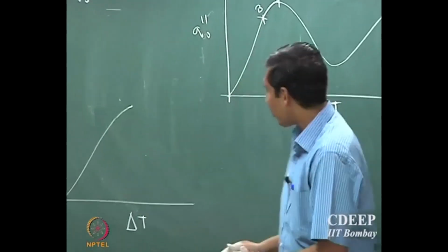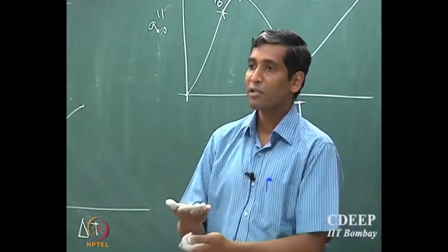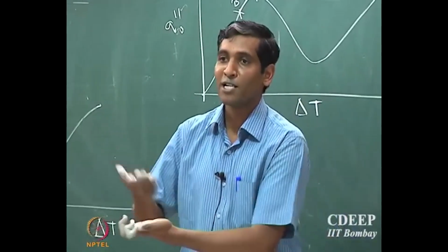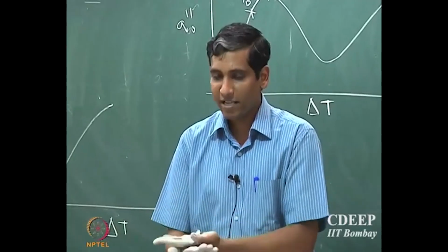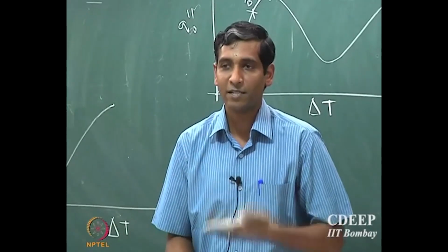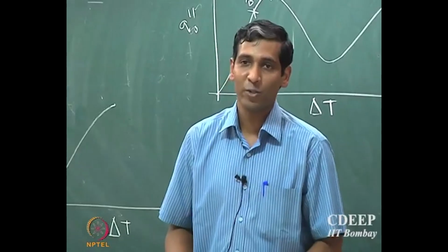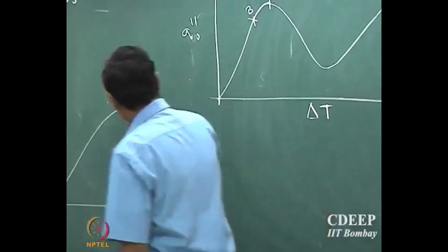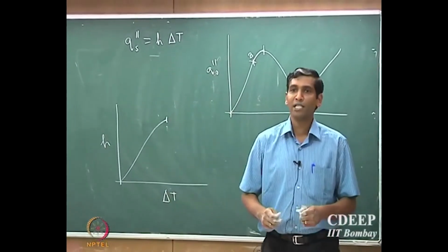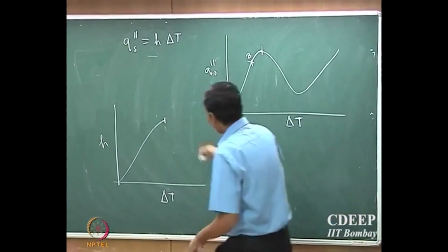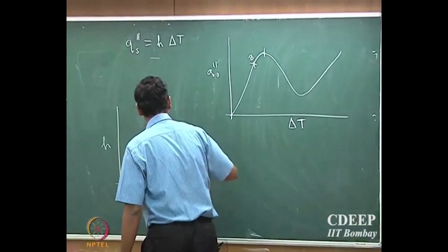The decrease is because the contact is not completely fluid, it's not completely vapor, so there's going to be a mixture of both, and the net effect is that the extent of heat transport is going to reduce. Therefore, at the inflection point you reach a location where there is a maximal heat transport coefficient, and then the heat transport coefficient starts decreasing.